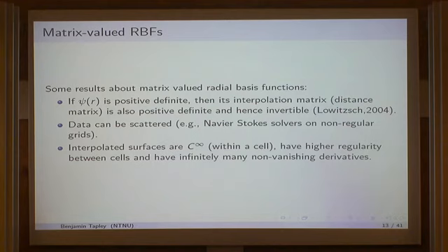Again, the data can be scattered, so we don't require a regular grid to do our interpolation on. So this is very good when we're looking at Navier-Stokes solvers on non-regular grids, and in this scenario, polynomial interpolation becomes very cumbersome. And again, we have C-infinity surfaces with slightly higher regularity between cells and infinitely many non-vanishing derivatives. And this is good because in some particle models we need the derivatives of the fluid fields to specify